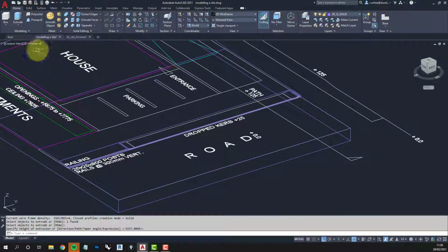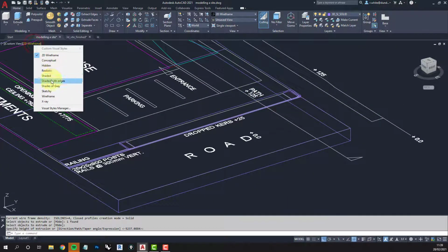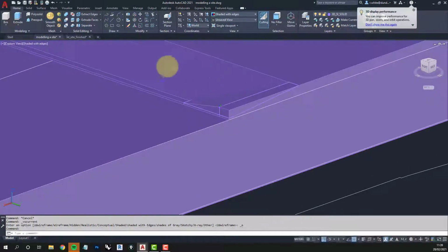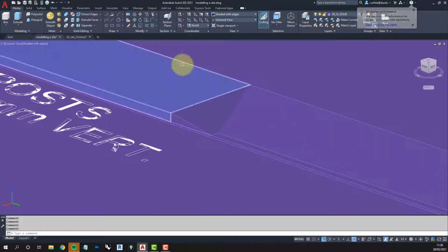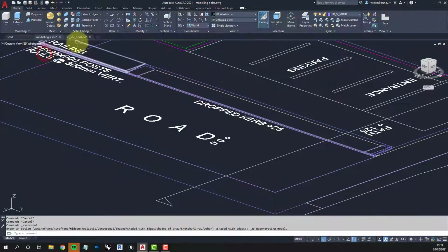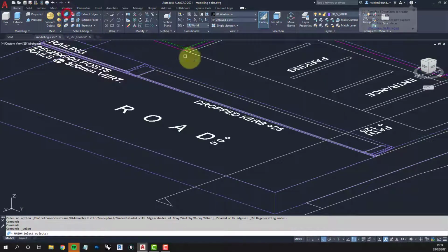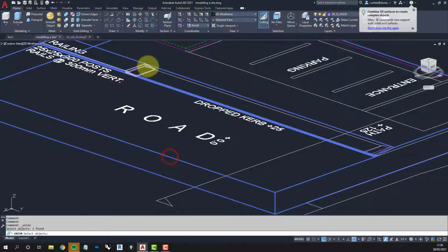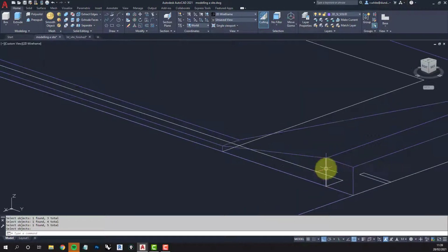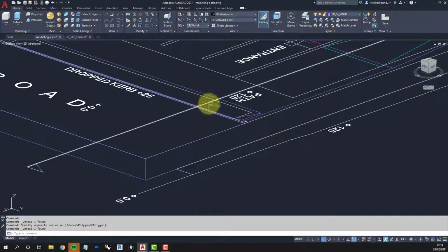Okay, if we shade it now, it'll look tidy, but it will need joined together really. So we can see the shapes looking okay. Okay, but you would then merge those together. So we union, pick the big shape and the two smaller shapes on this side and the two smaller shapes on this side. They all merge together and it's very tidy. A couple of lines extra here that we drew, we can delete those.